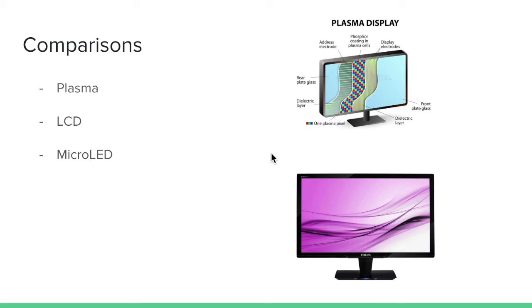Since each pixel in OLED screens produces its own light, they can produce darker shadows of black than LCD screens can, which creates a higher contrast. Another thing that LCD screens suffer from is uniform contrast, which is how consistent the brightness is across the entire screen. Viewing an LCD screen from any angle that is not straight on noticeably lowers the quality of that screen, whereas OLED screens do not reduce quality based on viewing angle.